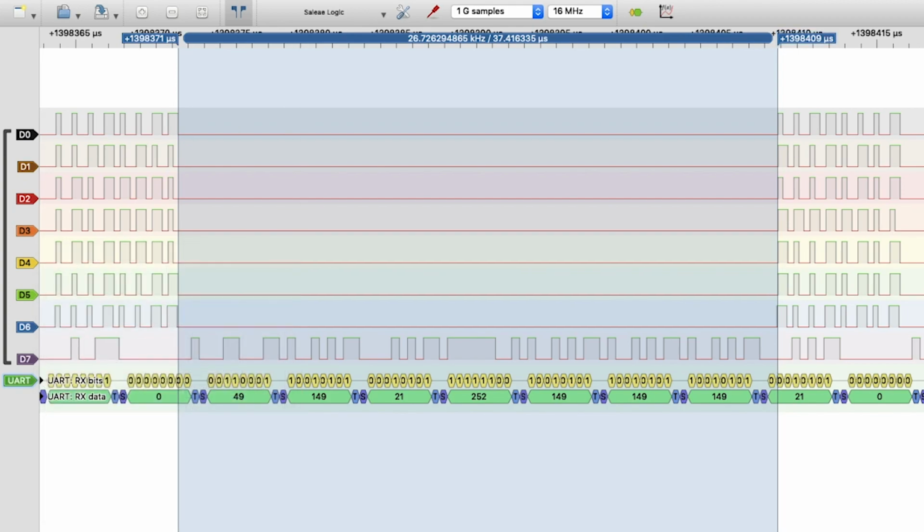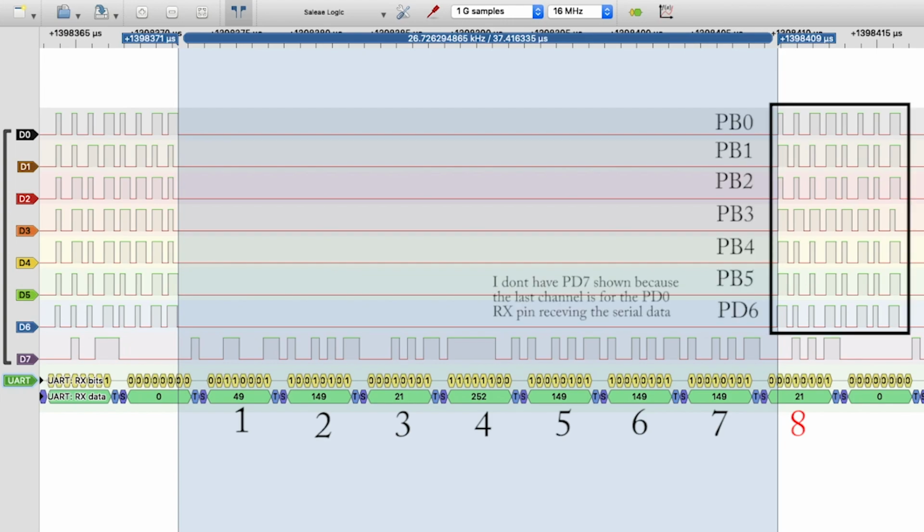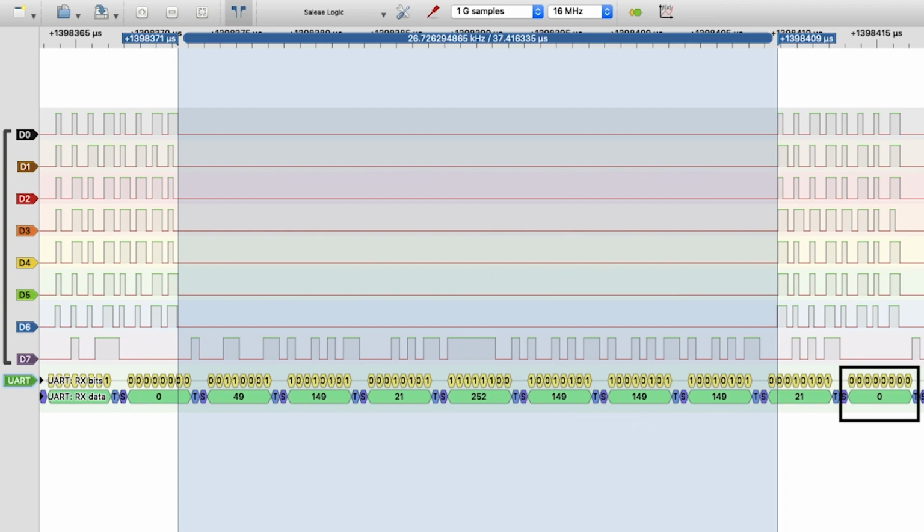Here's where the Nano directly reads the RX pin on PD0 at set intervals, gathering data for 7 of the 8 bytes. On the 8th byte transmitted, the function simultaneously reads and bit bangs the 8 bits in parallel onto the whole of port B and the 2 highest bits on port A, as PD0 is being used to receive serial data. And all this stays within the 40 microsecond time frame in which the NeoPixels don't yet latch. A 0 bit is then required after every 8 bytes of data to prevent reading errors through accumulated error shifting in the serial communication. Reading from such high speeds with simultaneous transmission and data reorganization is only possible with assembly, which is why the USART data register is not used to receive the data.